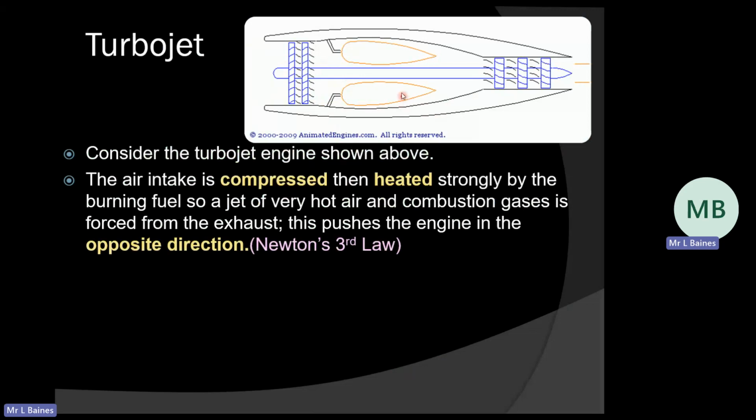We then also heat it strongly. We mix it with fuel and we burn that fuel off and heat that air up really quickly. Then we have very hot air forcing out of the exhaust. So we've got something that comes in at a relatively low temperature. We compress it, we heat it, so it's high pressure, and that is ejected out of the back of my engine. And that causes a force in the forward direction.